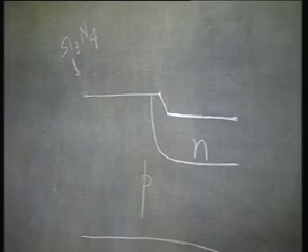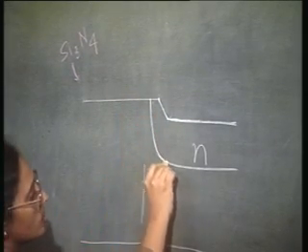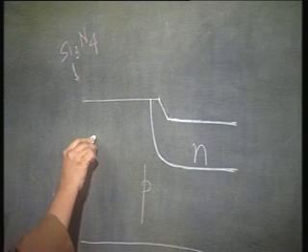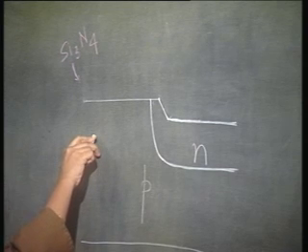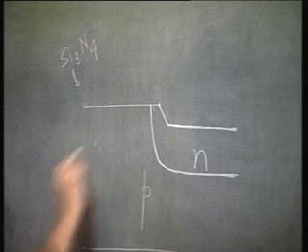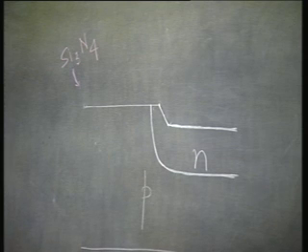So, now you have marked the two places. This is the region where you are going to form your N MOSFET, this is the region where you are going to form your P MOSFET, okay, and this step demarcates the two regions, right. Next is of course very simple. After you have achieved this, in these two regions now you have to have the field oxide and the area for the active transistor.